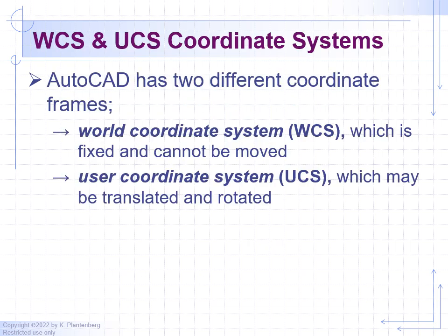So there are multiple coordinate systems in AutoCAD. There's the standard one that is kind of set up and it is global. This is known as the world coordinate system. This is going to be a fixed system. You can't change that. When you start up your screen, that's where your axes are. They're sitting on your world coordinate origin.